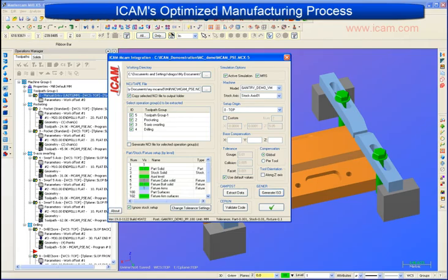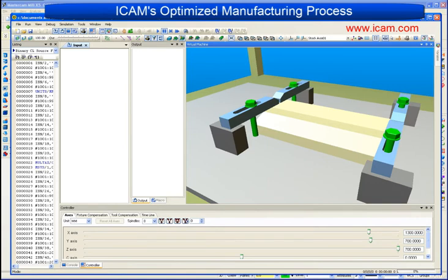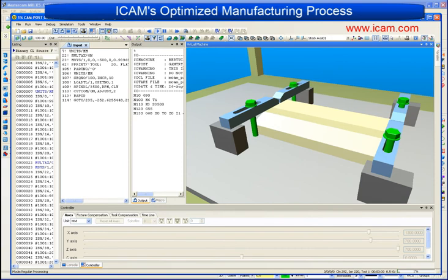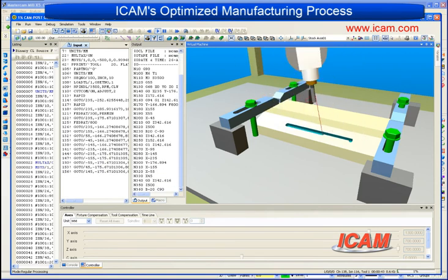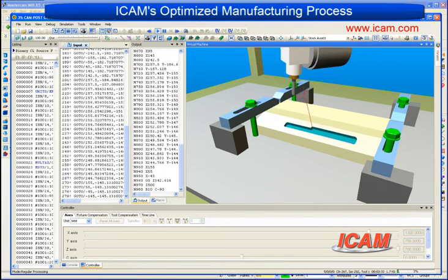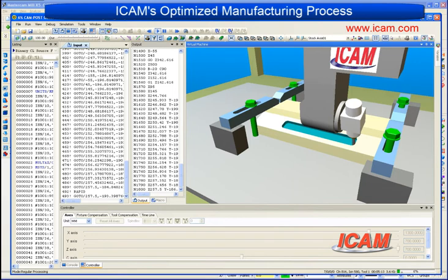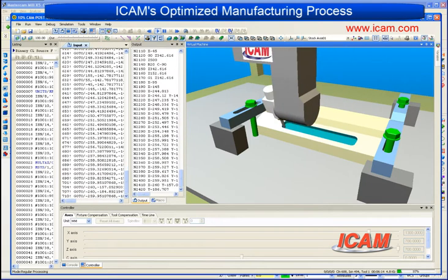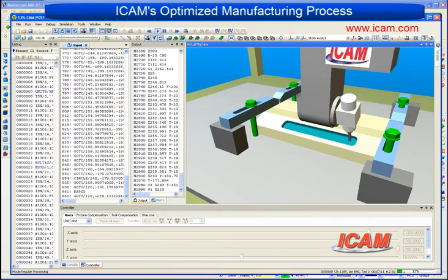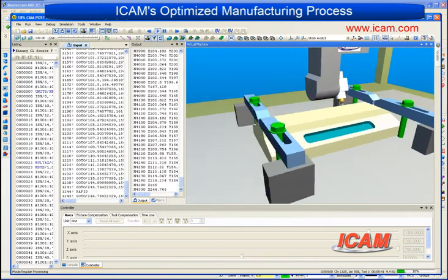Again, I'm running the extractor. In the middle, the input window shows me the code from Mastercam. On its right, the output window will show the G-code as it's being produced. Notice how the machine will react at every beginning of a toolpath. The post processor will look ahead throughout the whole toolpath and identify if collisions would occur. And if they will, then the post will automatically retract the tool, position to the alternate path, as you can see, and thus avoid collisions.